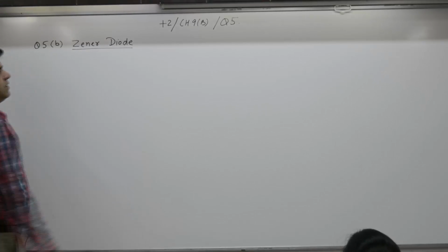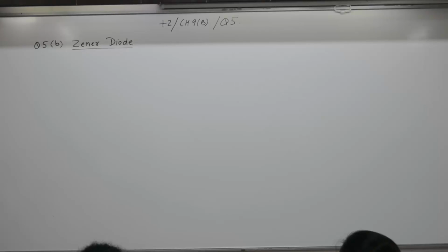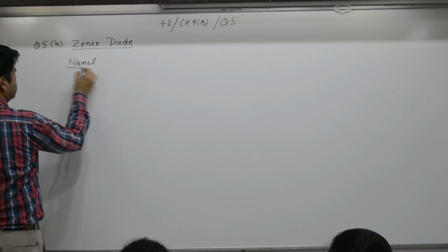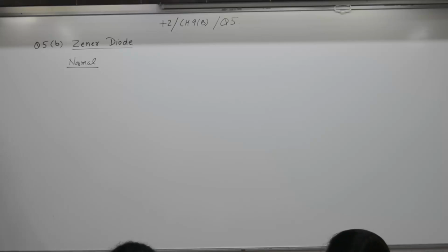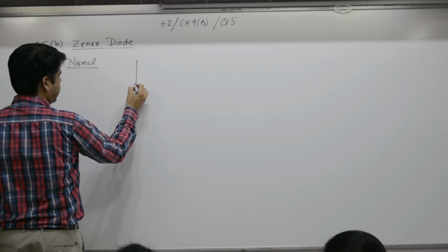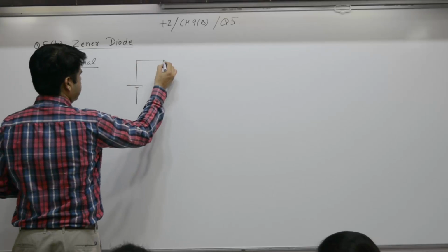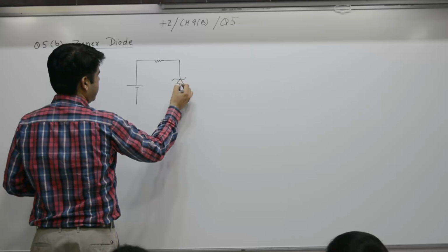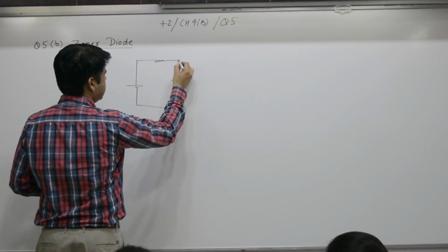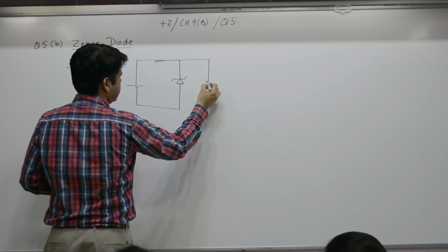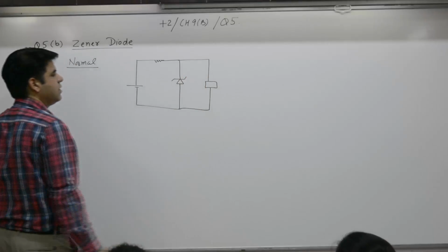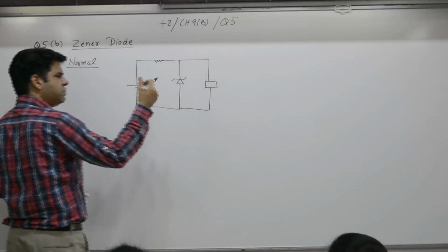How do you address it? That means in case you use a Zener diode, under normal condition, what is the status? Normal conditions. You have what voltage? Say 210. You are using a Zener, forward bias or reverse bias? Reverse biased. Connected in series or parallel with the device? Parallel with the device. All objective questions.